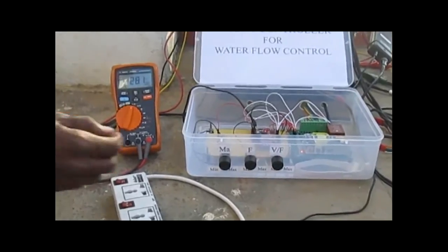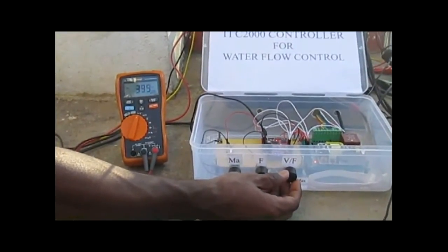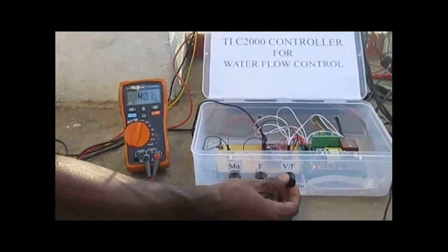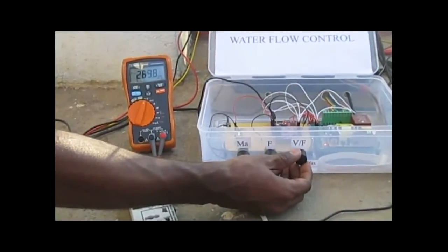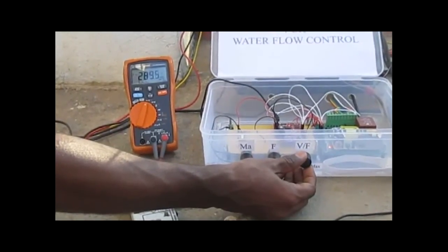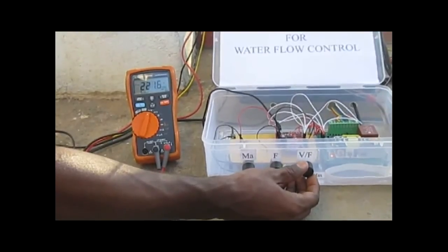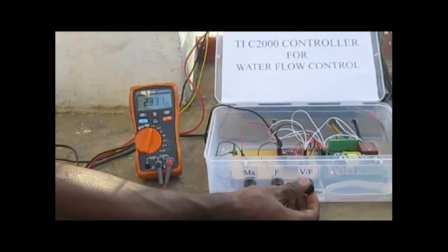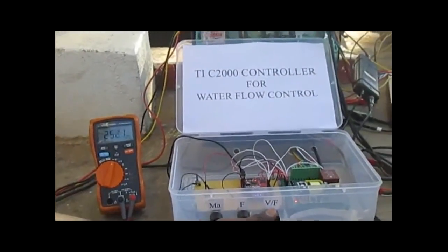Now we are watching the inverter, which is a Semikron based inverter, and we have kept some Agilent power oscilloscopes and the Fluke power quality analyzer for performance analysis. Now we are watching the sequence of operation. The input to the rectifier is turned on, and the output from the inverter is turned on. There is an optional manual control apart from the automatic control, to vary the flow. Basically, it varies the frequency and voltage of the induction motor.